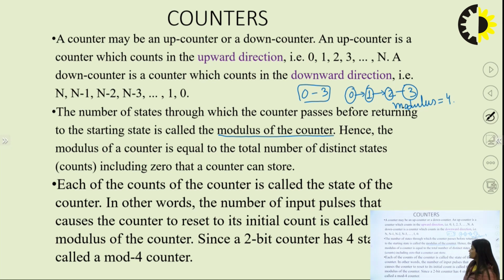Modulus is nothing but the number of states. If a counter starts from 0, then the first state 0 is also a count. So we have understood a very important concept: the number of states is equal to the modulus of the counter.